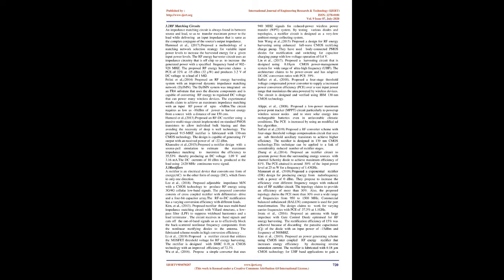2.3 Communication Protocol. Shuiying et al., 2015, proposed a topological structure layered configurations, TSLC, routing algorithm to improve the quality of WSN data transmission performance based on the topological structural characteristics and optimization of network layers. Using cross-layer design, the co-processing of layers is achieved by extracting the information of the nodes in the network and MAC layer. The results reveal that it saves the power consumption of the entire network, enhances the performance of the network, and also prolongs network lifetime.